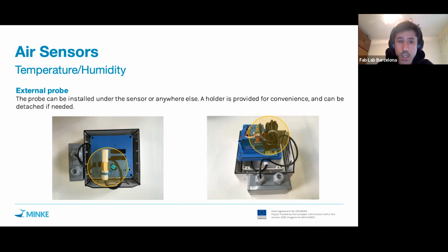This will affect the temperature readings for sure, and you will see that the sun radiation will heat up the enclosure and the temperature probe itself. So if you don't want the sun to affect it, you can even place it inside of a Stevenson enclosure or similar, and you can place it in any other spot with plenty of cable to move it around.